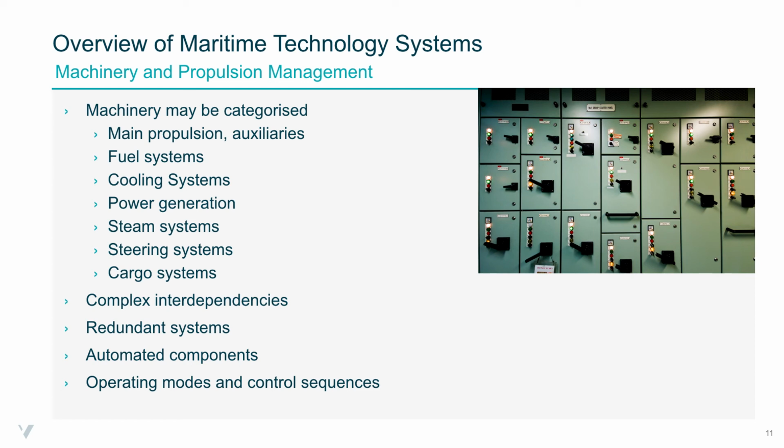Cooling systems, taking jacket water from the main and auxiliary engines, will have the ability to monitor that outflow temperature and divert that cooling water to a heat exchanger, or return it to the loop, depending on what the set point is, and doing a comparison with the measured temperature.